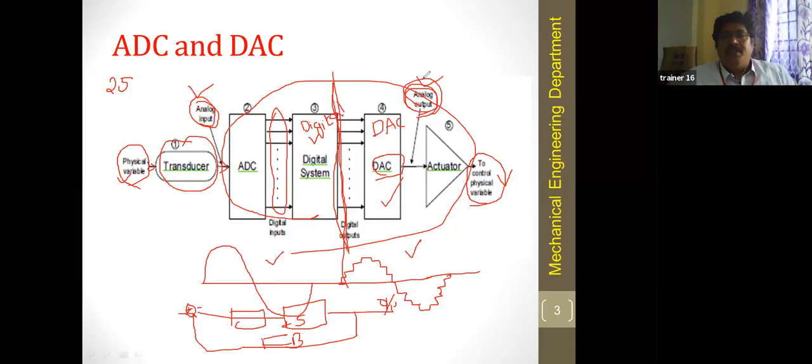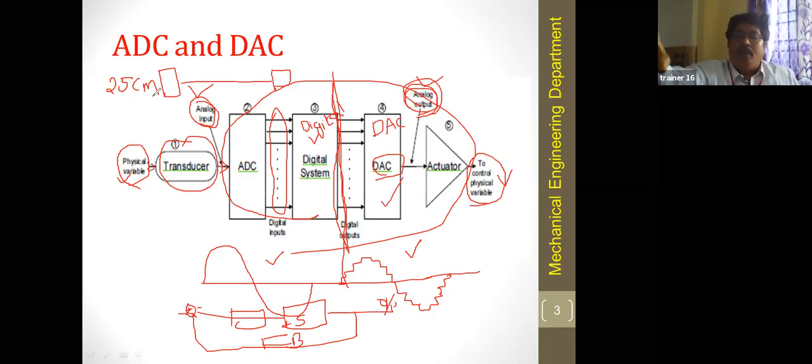With the help of this, we can get the correct timing. Once the piston moves forward 25 centimeters correctly with that pressure, the piston pushes the product some particular distance. If the pressure varies, the distance also varies automatically, and thereby the product will not move to the correct location.